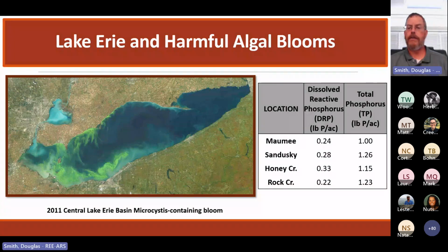To a large degree, that's true. We've done a tremendous job at reducing erosion and total phosphorus entering the lake. However, what we didn't realize was this soluble phosphorus, which seems such a small component of the phosphorus, is very bioreactive, and small amounts of soluble or dissolved phosphorus can drive algal blooms to a much greater extent than the total phosphorus.